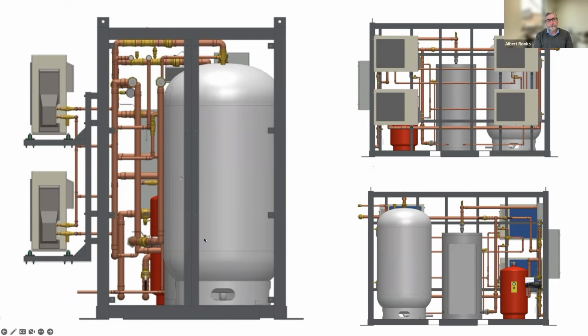But doesn't this look familiar? Lower right-hand corner, the heat pumps are on the back. The heat pumps are giving all of their high temperature water to that big primary storage on the left-hand side. Primary storage is piped over to that swing tank. If we can drill in any closer, we'll see that there is a recirculation pump on board, and a temperature mixing valve, or temperature maintenance valve, on board. The red tank is expansion. Everything there is on board.